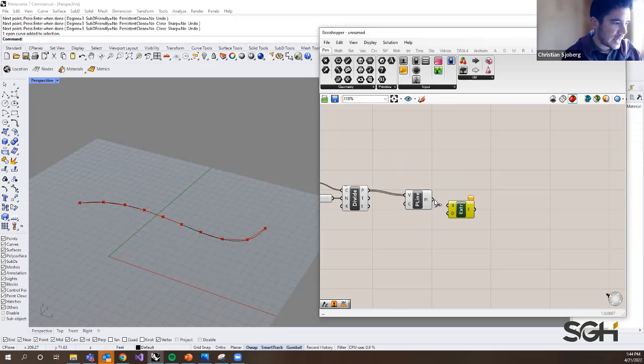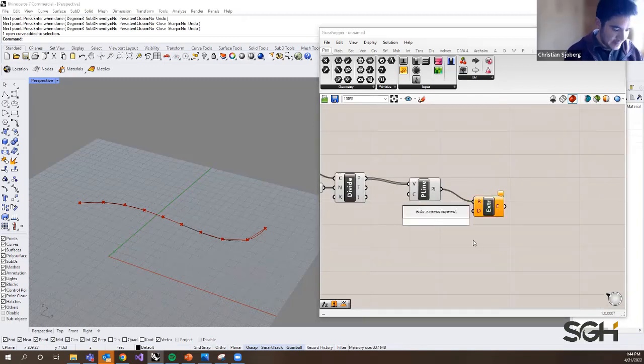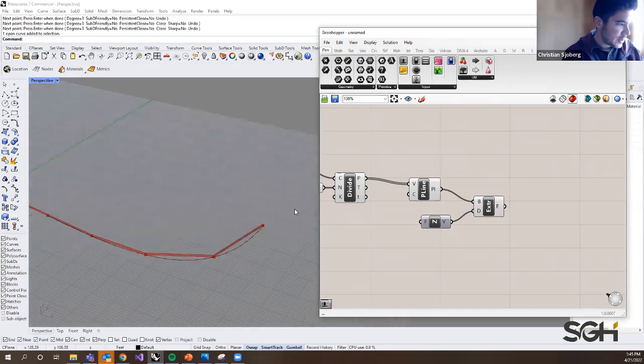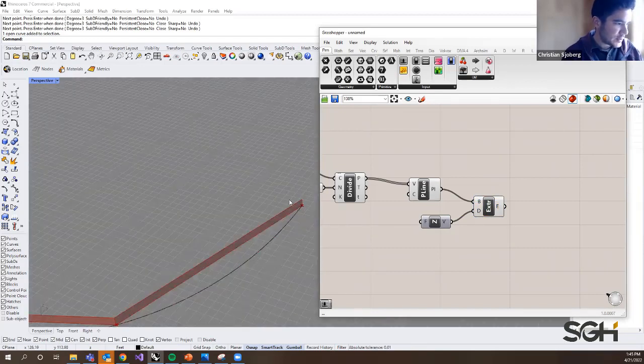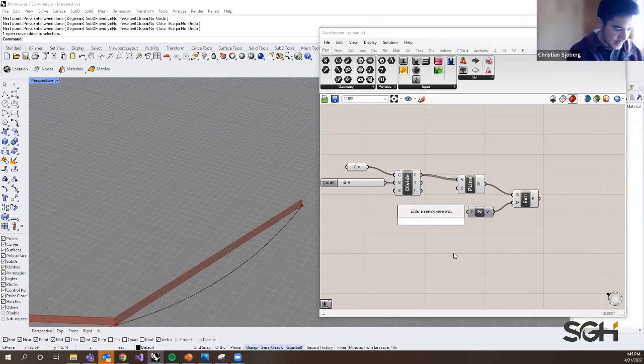Extrude basically just means pulling it into 3 dimensions, right? So we're going to take that curve and pull it in the Z direction. I'm just going to double click, type the letter Z, and now I'm saying the Z direction. You can see that's done 1 unit. These two squares are like a foot, 1 unit. And then we can say, let's go more than that.